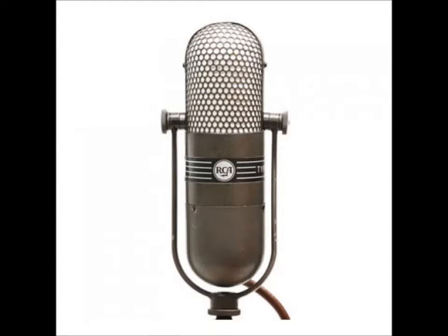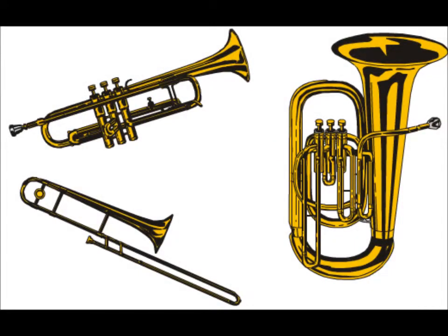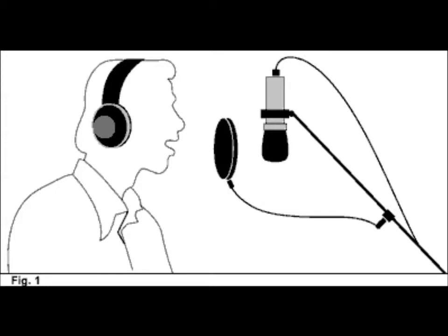Ribbon microphones don't generally need phantom power, although some have preamps which do of course require a power source. Use ribbon microphones for shrill or brassy sources, as they seem to smooth out those sources. You can also use them for vocals, live or not, when the singer isn't very close to the mic. A big ribbon mic has long reach.